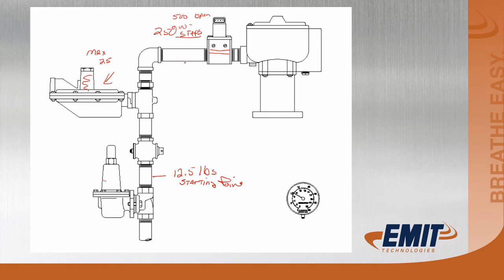Now the next thing is, on most carburetors, you're not going to want any more than 5 inches of water column. So you would take this cap off and you would adjust it with the engine idling so that you had 5 inches of water column. Now at this point, you've got it set, you're running at 5 inches of water column pressure going into the digital power valve.